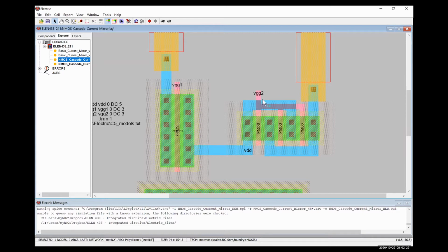I was just counting the widths incorrectly, so I would like to explain that really quick. Effectively, we're just counting the width along the side of our gate here. So this is 10, and then over here we have the shared source between these two transistors. And so we have 10 on this side and 10 on this side of our gate. So that's why it's 30.